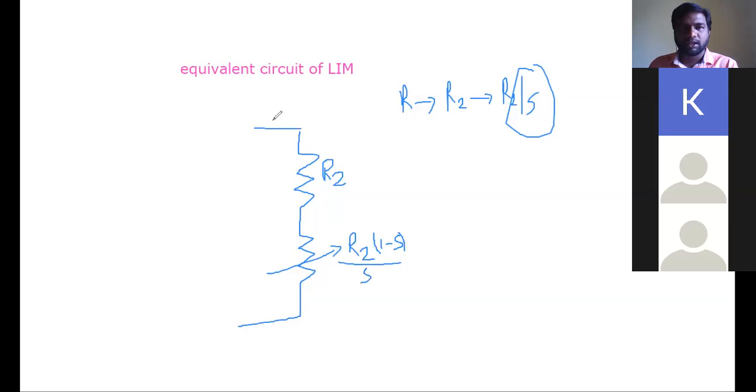So now here the current flowing is the I2, that is the rotor current, right? So now R2 is nothing but the copper loss, which is a constant one that depends upon the I square R, right? Copper loss is nothing but the I square R, that depends upon the current flowing in the winding as well as the resistance of the winding, and this gives nothing but the output of a machine, right?